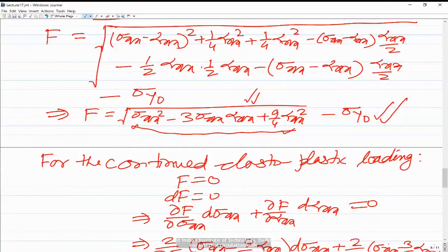You can have the tolerance on the net force vector, or on the displacement vector, or on stresses. The most common ones are the displacement and the force, and that is an input, something like a displacement tolerance of 0.5. Okay, sir. Thank you.